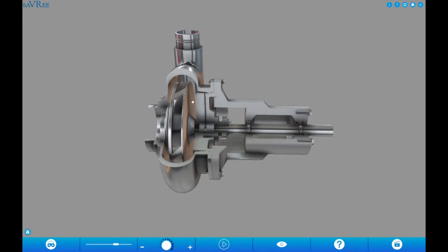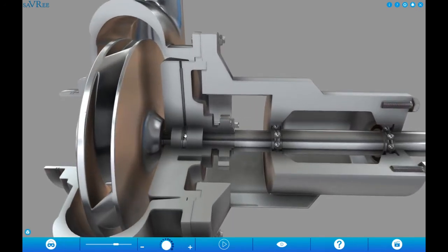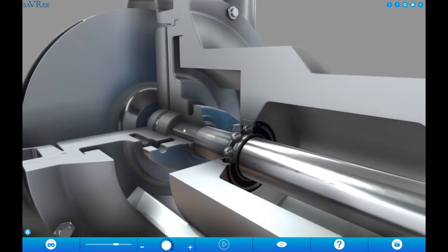So if we do not have any such device, a compression packing or mechanical seal, the water will push out from here, because we need something which rotates, and to give the rotational possibility, we have to give space for rotation. And if we give space for rotation, that means there is space for the water to come out as well, because what we have is very high pressurized water in this part of the pump.